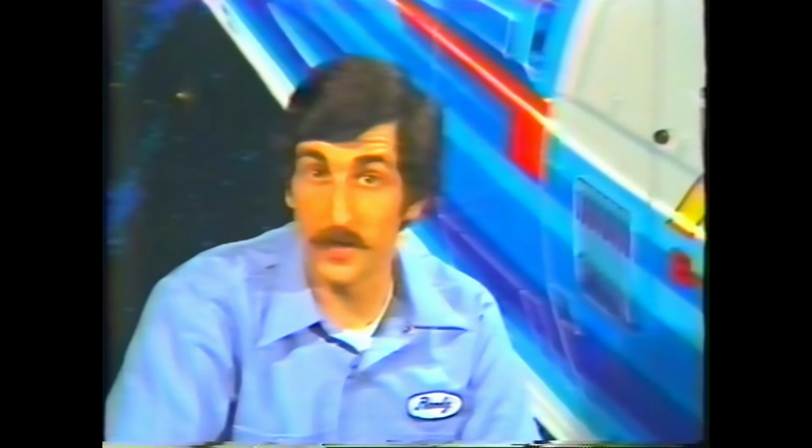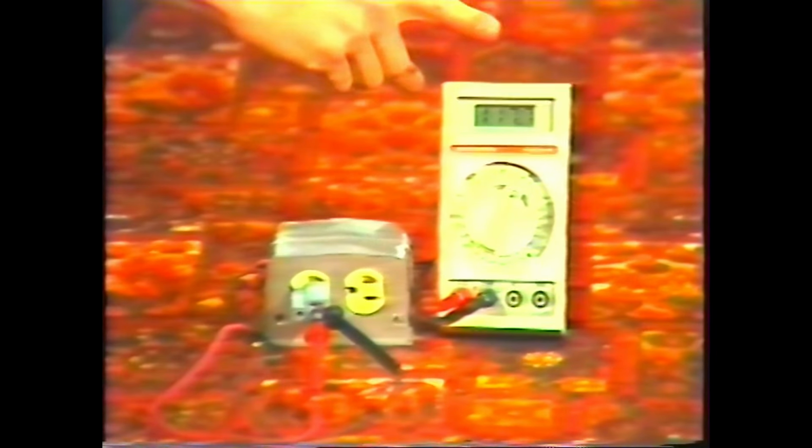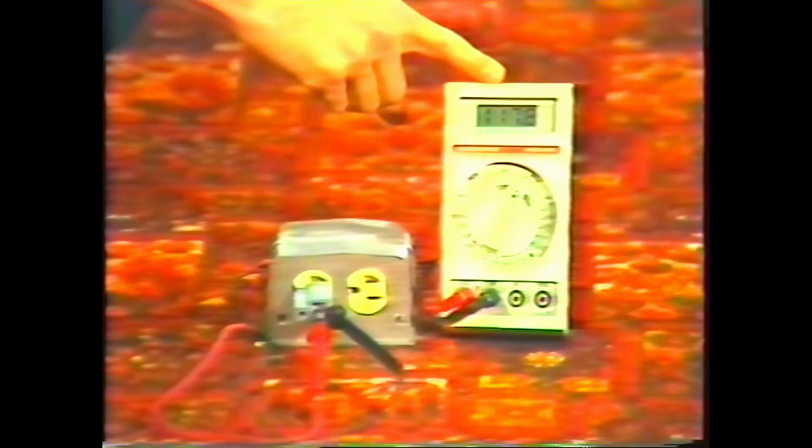Say, for instance, we wanted to measure the voltage from a floor receptacle. Well, we know that that voltage is somewhere around 120 volts AC, so we'll set our meter to the 200 volt AC range. With the meter set on 200 volts and the red and black leads inserted into the AC receptacle here, we can measure the voltage and read it right off of the meter. In this case, it shows 117 volts.